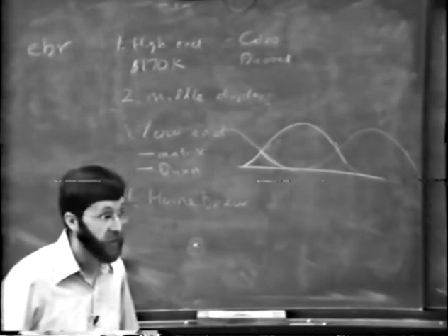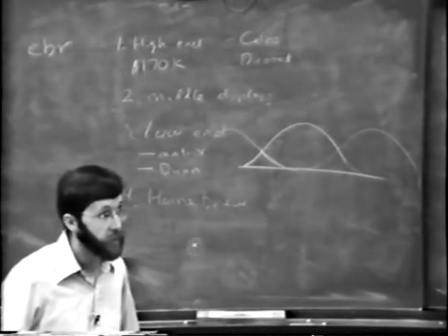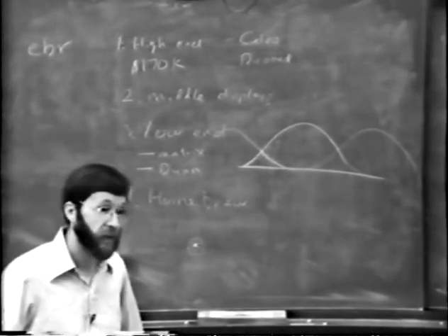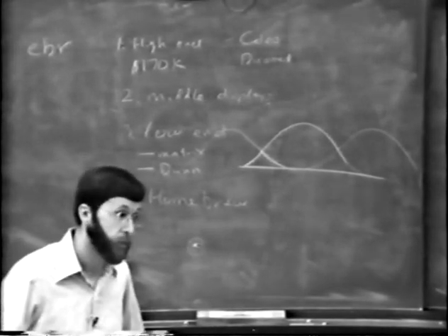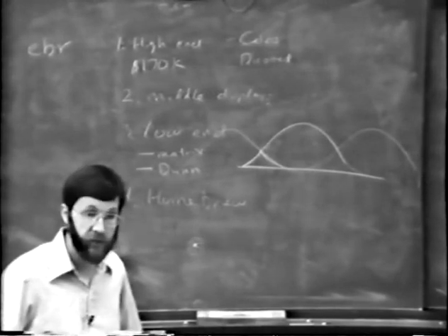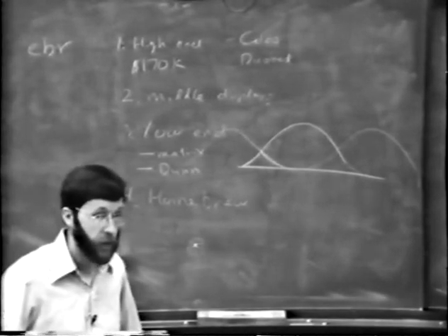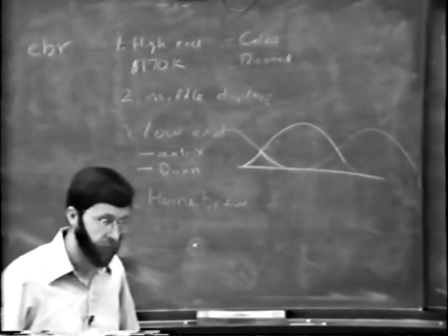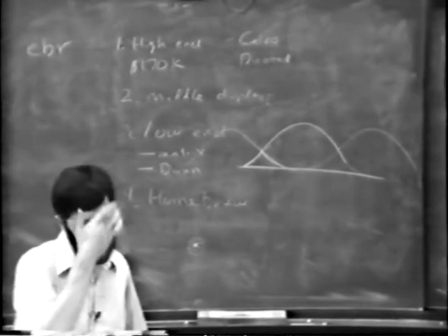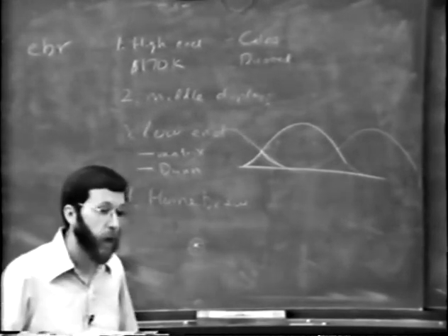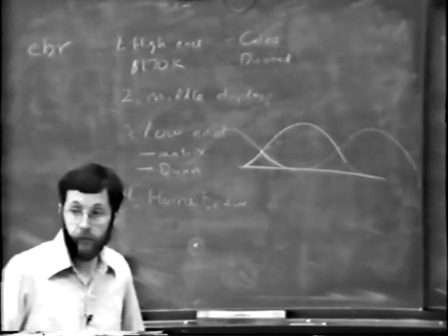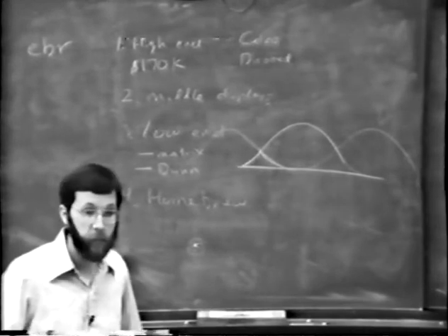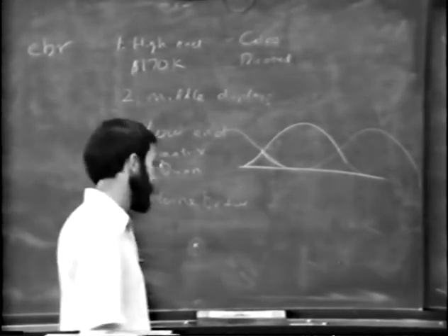Now, what's the chief difficulty, then, with the lasers? Well, there are some difficulties that we haven't had experience with yet as we're trying to get this thing built. How stable are the lasers, both over the long term and the short term? As, for instance, there is a noise in the laser, and some lasers have a substantial amount of noise in them. Now, there are feedback systems to compensate for the noise. The chief problem, though, is that of deflection of the beam. If you're going to write on film, you must mechanically deflect the beam. All right, now, what is the problem with mechanically deflecting the beam?